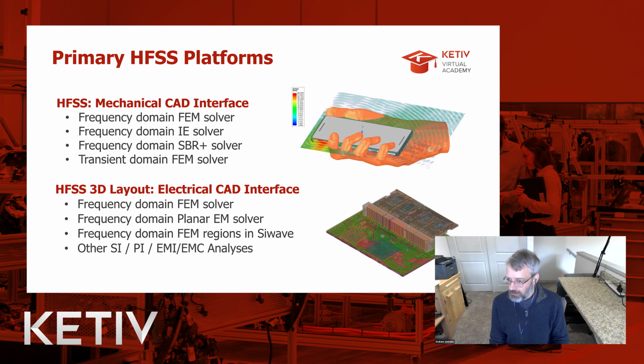And then a secondary interface called HFSS 3D Layout was created to make it easier and simpler to import 2D PCB information from traces directly from ECAD software where it was maybe designed elsewhere, and pull it into HFSS into this platform called HFSS 3D Layout. And using that, you have the same solve engine for HFSS essentially, but it's slanted towards this sort of planar situation. So we have a planar EM solver, and then other links to SIwave and power integrity analyses or EMI, EMC analyses, which we will not be covering today. We're going to focus mostly on antenna design.